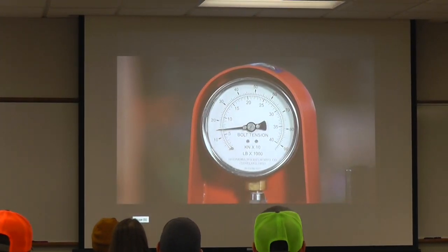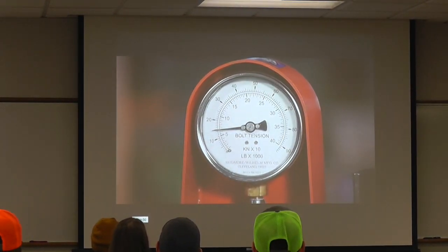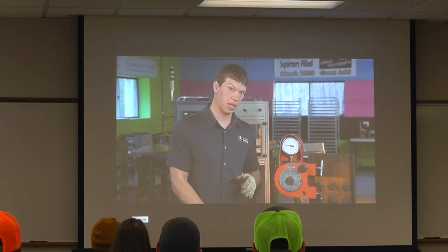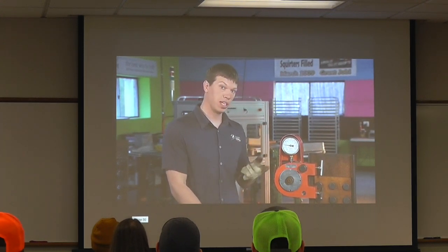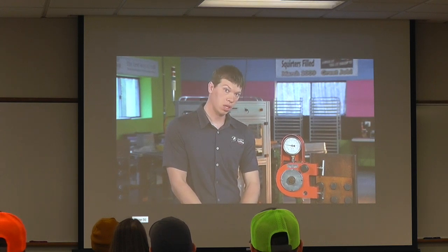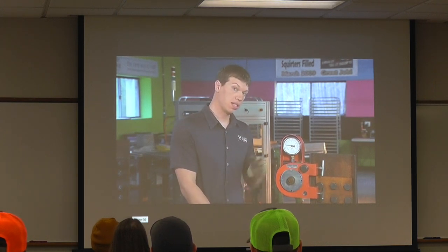We have a tension of about 15,000 pounds. So we're not even close to our minimum of 39,000 pounds, which we're shooting for. So there's two things we can do here. The first being increase the torque setting on our gun, or we can lube the bolt assembly. In this case, we're going to lube it.